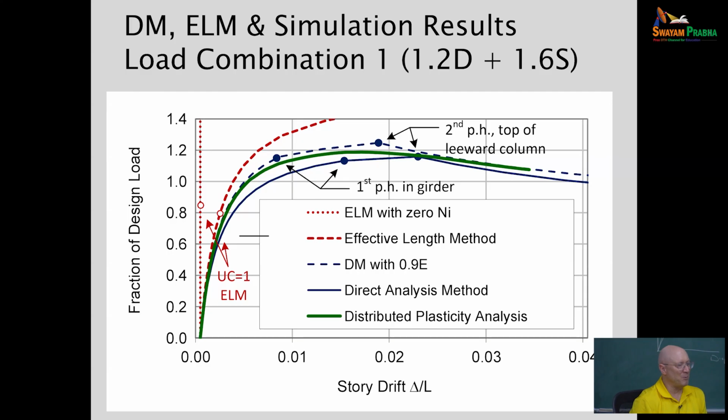But with things like the beams, the connections to the beams, if we want to check out-of-plane strength of the column, is that affected by the moment in the column? Well, the moment's quite a bit different in reality than the moment we calculated with the effective length method. So we're kind of missing all that. And so the thought was, okay, it's very far from perfect, but for gravity-only load combinations, let's require a notional load.